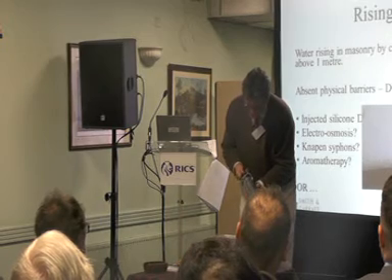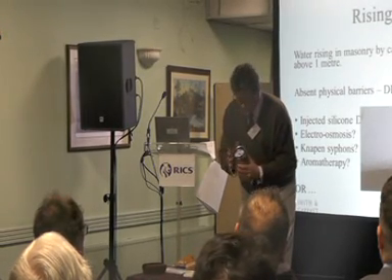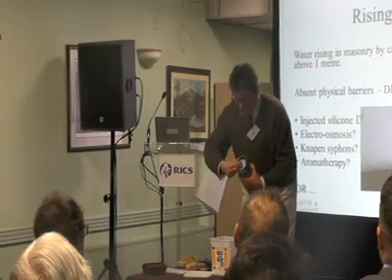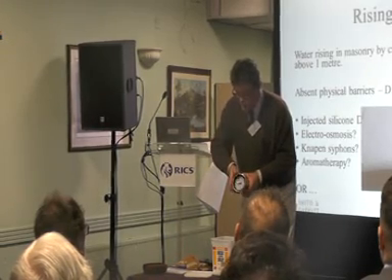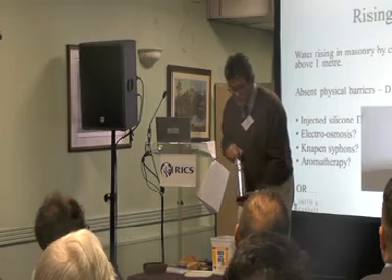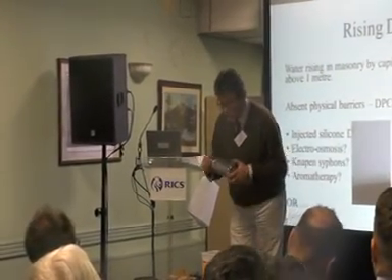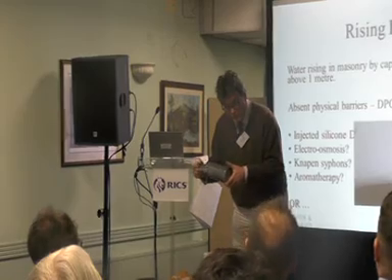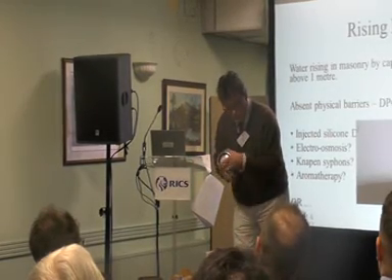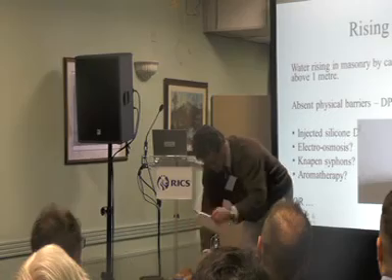The carbide extracts the moisture and makes acetylene gas. The acetylene gas comes out, puts up the pressure, you read off the pressure on the bottom. Absolutely reliable. All of us expert witnesses use this, and if you don't use this and you are an expert witness in a court case, frankly the other side will defeat you, because this is taken as the definitive test.